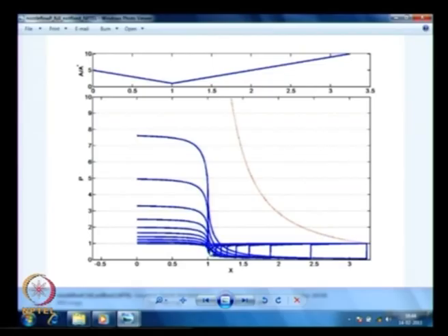Why will the pressure at the throat decrease for initial cases? Initially it is subsonic, where in the very first case there is no flow, so pressure is the same as atmospheric pressure. After that there is some flow, but it is all subsonic, so it will go below and then increase to atmospheric condition. That is the reason it is going to decrease initially, and after that all the curves will go up. Only if you plot it better you will see it nicely. I will just show you an animation instead.